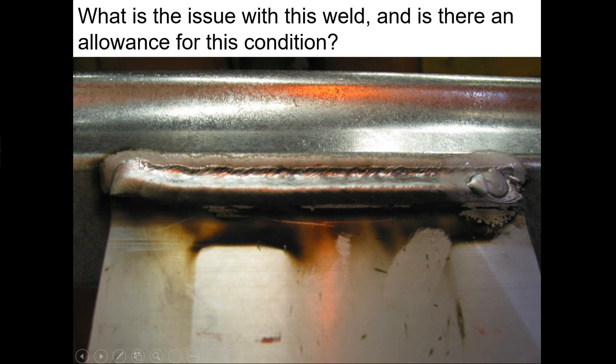This one requires rewelding. It requires a nice TIG pass to go all the way across with a proper termination about there. And we'll give a good look to that while we're there. But this is not something you're going to sit there and fix all night. This is something where there's a problem with the gun and it needs to get addressed. No robot tech is going to program something that's going to come to you looking like that.